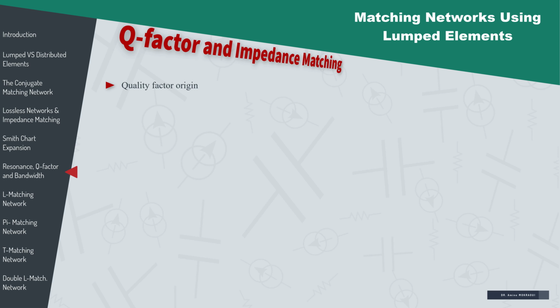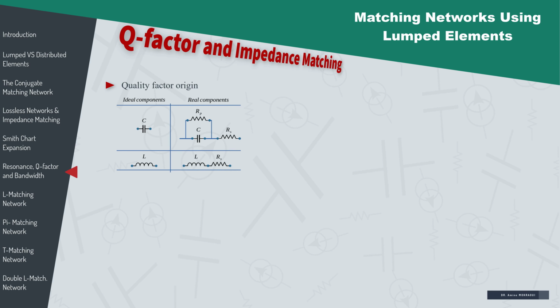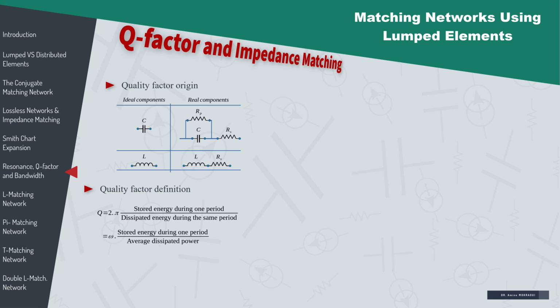We already know that ideal reactive elements do not consume energy because they do not have any losses. However, real reactive elements do have losses. For example, an inductor has an inherent serial resistance, whereas a capacitor has parallel and serial loss resistances. The quality factor, or Q factor, is a measure of those losses relative to the stored energy. If we consider a cycle of sinusoidal excitation of angular frequency omega, we write Q equals 2 pi times the stored energy during one period over the dissipated energy during the same period. Or equivalently, the Q factor equals omega times the stored energy during one period over the average dissipated power.